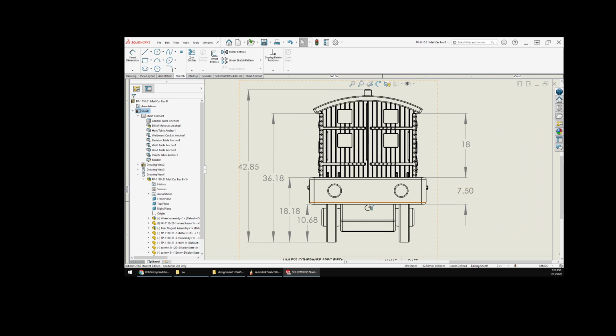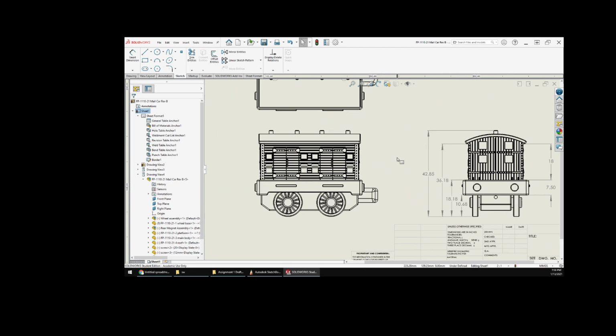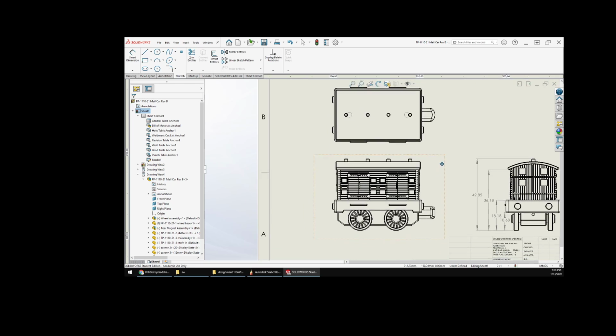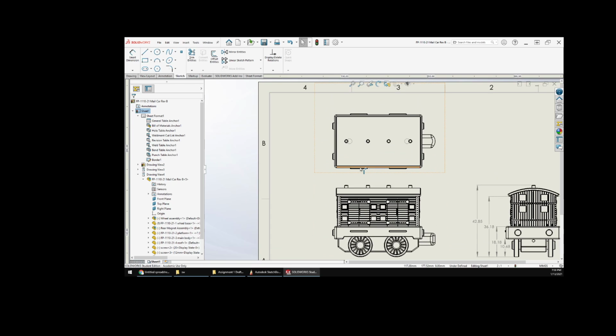Now, the challenge would be in an assembly drawing, do I need to have these numbers? I would say probably not unless I need them for some reason, because I'm going to blow that part out and give all those dimensions. So again, these are more generalized dimensions.